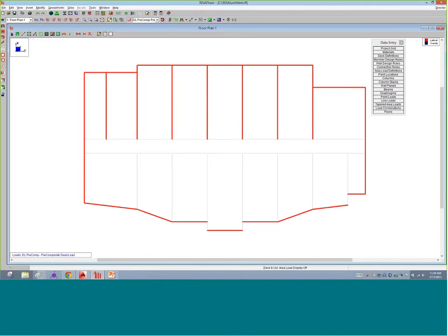So I'm almost done, but you'll notice on this DXF underlay, I can click to intersections. If I have other elements crossing that, I could have clicked to that. The DXF makes it really handy, and it's so easy to lay out a DXF quickly, and most people are pros at drawing in AutoCAD, things like that, real fast. So if you do that over there, you can easily underlay it, and it makes it really helpful.